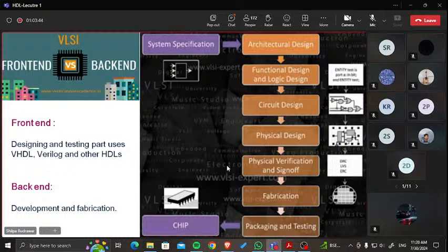Yes, ma'am. हम्म? तो आपने जो कोड लिखा है यहाँ पे वो क्या रहेगा? Because if I am writing something in if else, it will generate its mux or encoder. If I am writing a case statement over here, it will be implemented as a priority encoder. So for each and every syntax there is some dedicated hardware, and that way it will be converting. Translation means क्या होता है, मैं फ्रेंच में कुछ बोलती हूँ तो इंग्लिश में उसका कन्वर्जन के लिए कुछ तो होगा. So that way, if I am writing code, if else statement, case statement, whatever the loop statement, exist statement, that is having its own hardware.